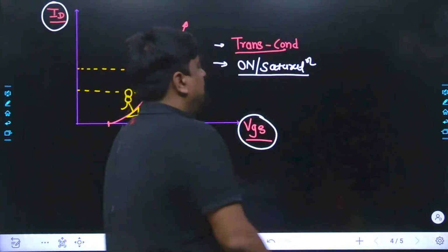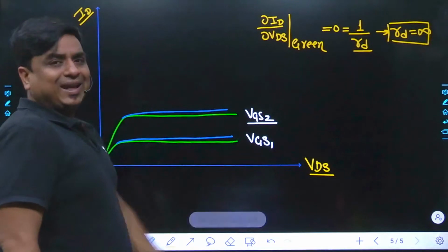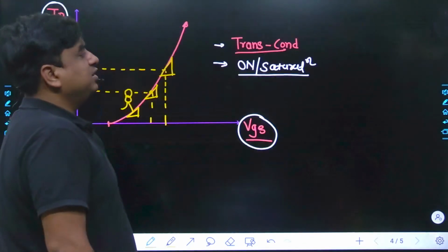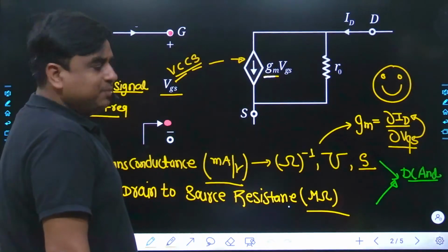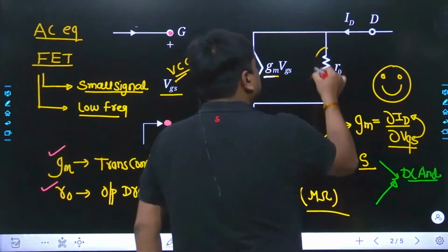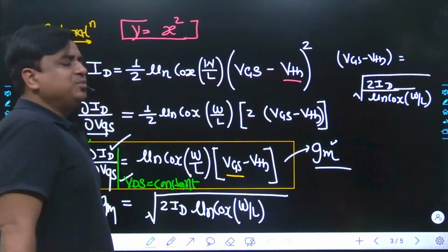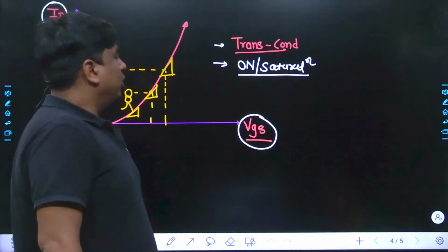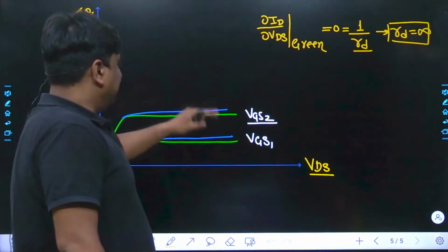Virtually speaking, when the output characteristic is flat in the saturation region, RD must be removed from its equivalent circuit. Yes, I could have RD or R0, I could have just knocked it out. But many times the channel length modulation effect is also considered. Practically speaking, we get a slightly sloped structure.